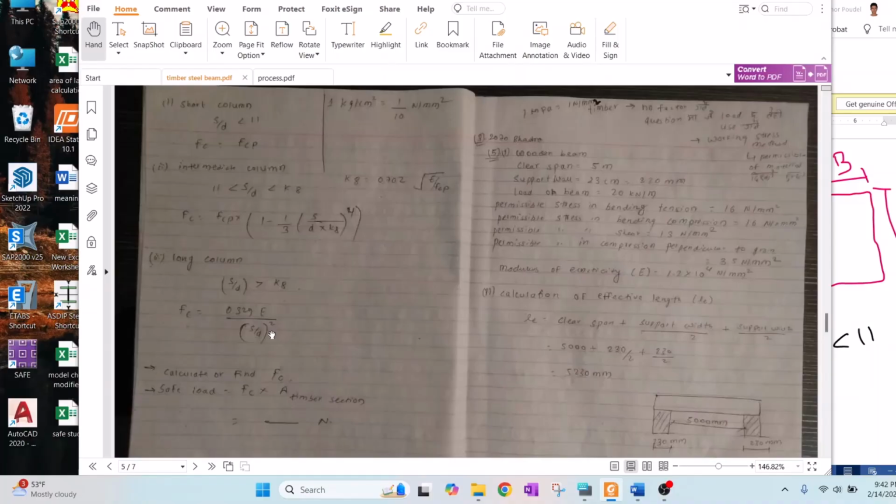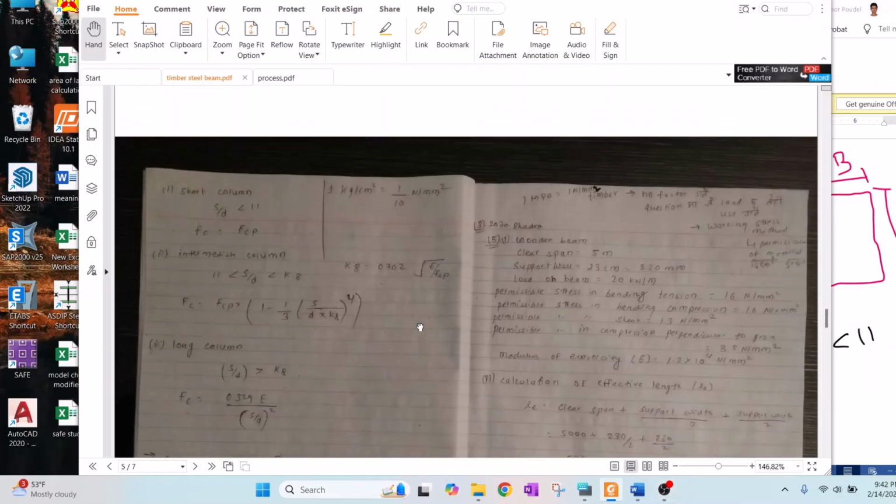There is just one difference while calculating the safe load. For a circular column, you just need to find the equivalent length of the section as a square. If the section is square, then you can use the same equation which is used for a rectangular or square column. This is maybe easy because we do not need to remember a large equation, and the concept is, I think, relatively easy in comparison to other questions.